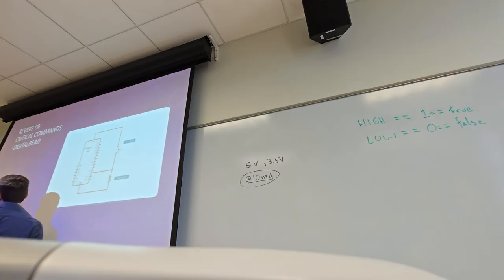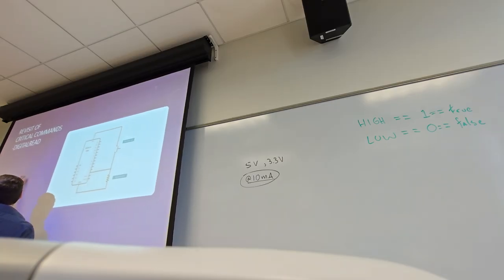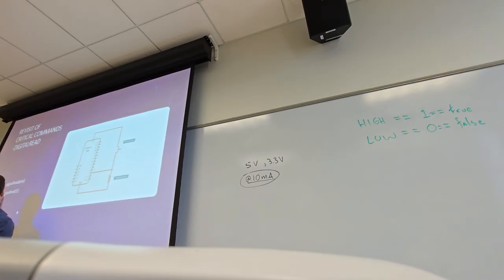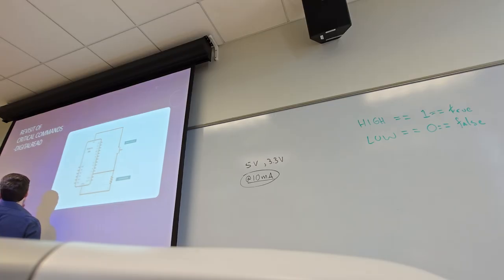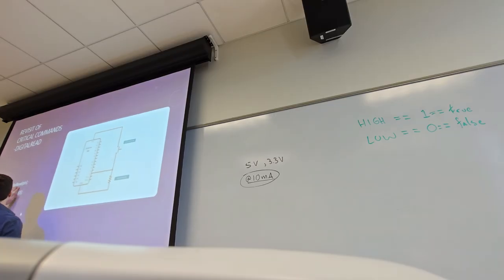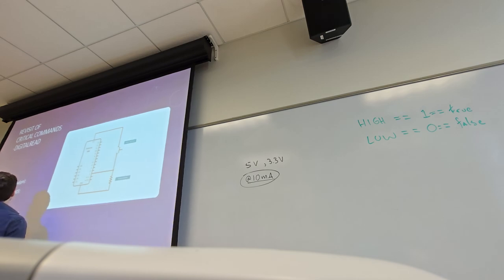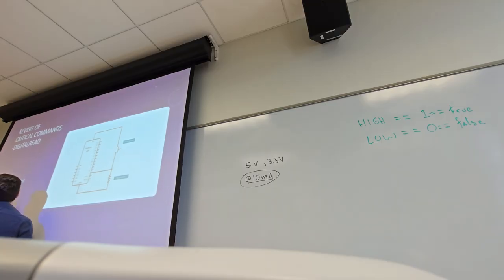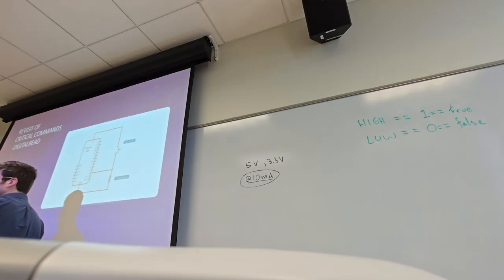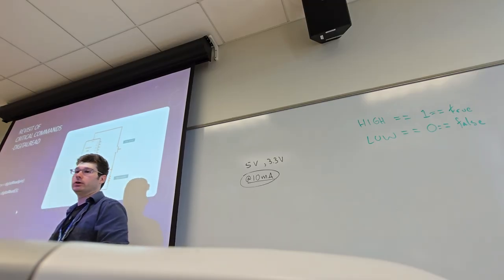digitalRead only takes one argument, the pin, whichever pin we previously configured as an input or an input pull-up. And then here we are reading that pin. Whatever the result is, high or low, 0 or 1, true or false, that'll get stored into this X. So on the next line down, if we were to print that or turn on the LED according to what is stored in X, it'll look at X, see 0 or 1, and then light the LED accordingly.